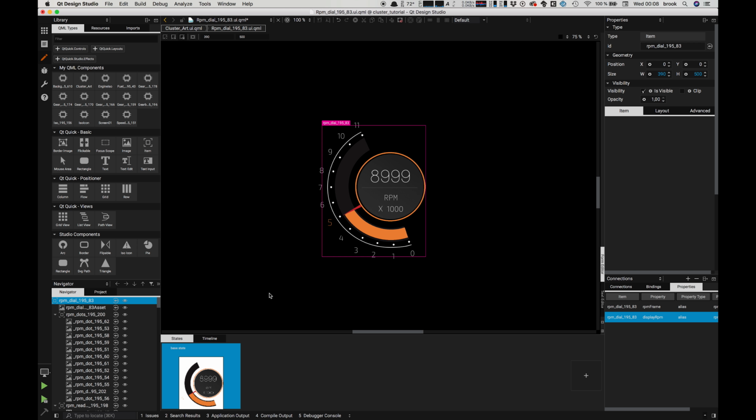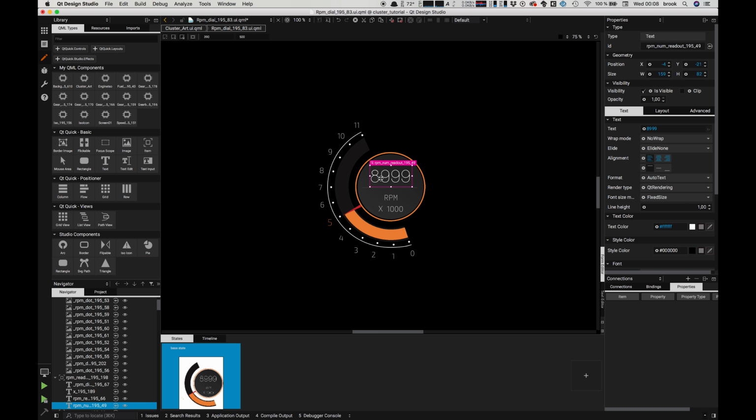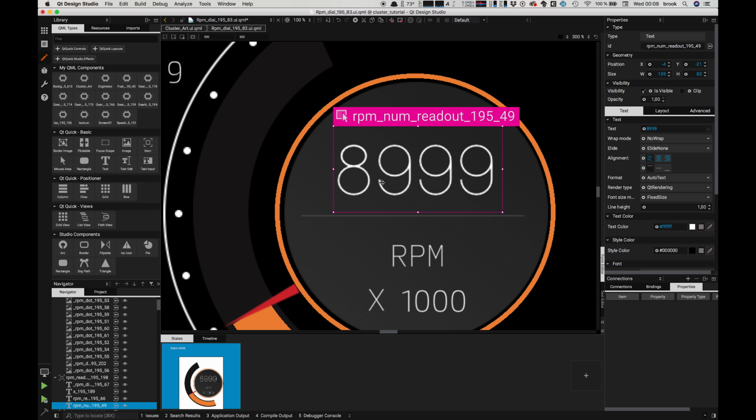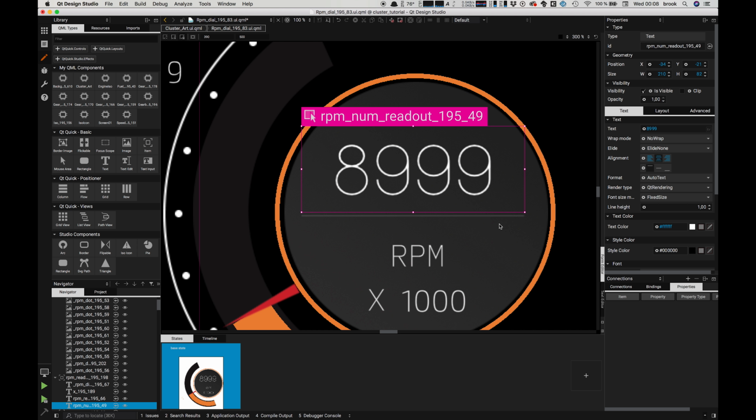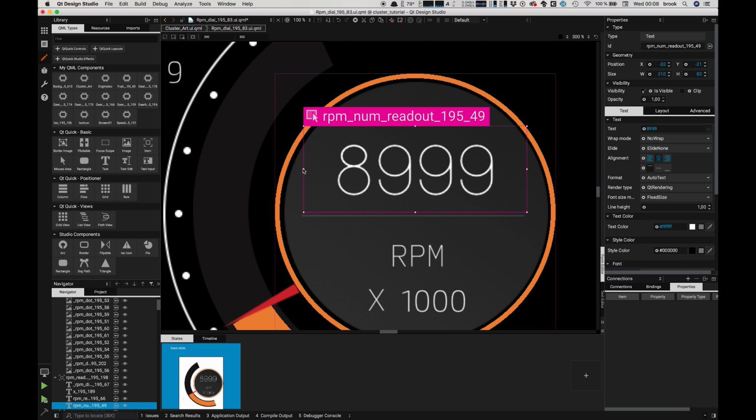We're going to fix this text object. So what we want to do to start with is just make sure that everything stays centered in our text object while the number's changing. So let's drag out the text box to fill up our button, our background. And then we're just going to center it up with the alignment here. And one thing to note is that I am using a fixed width font, otherwise the numbers would jump around in their position with every new frame. So with a fixed width font, we know that we're going to have a nice smooth animation.